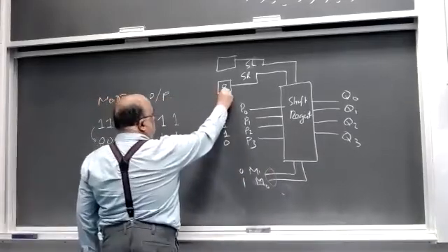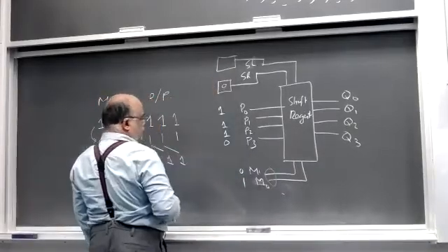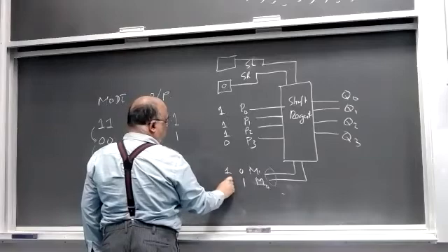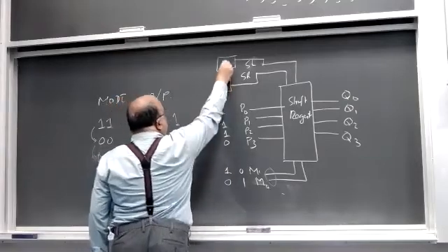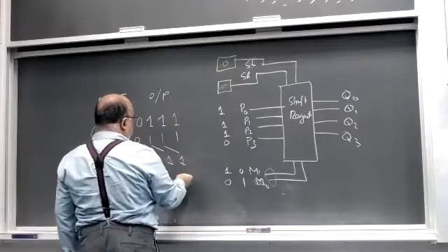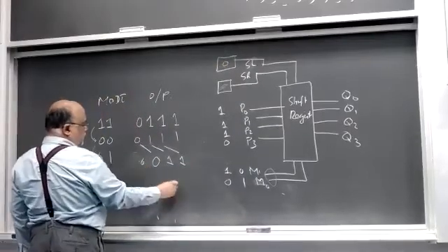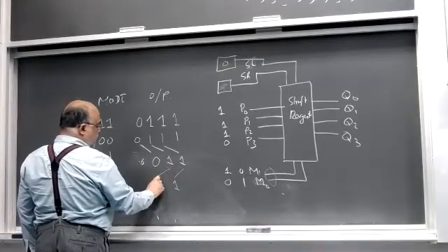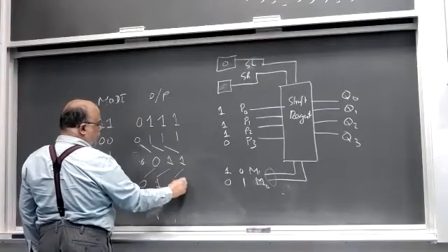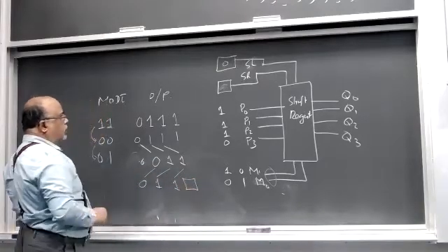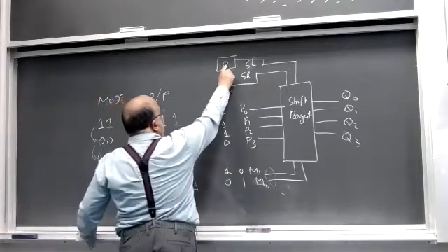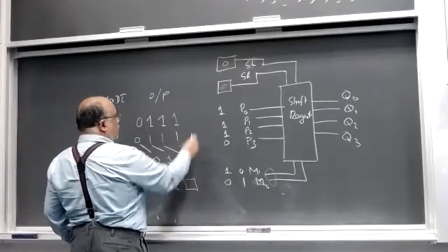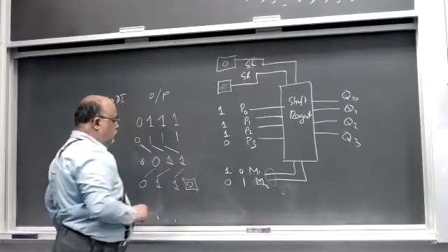उस वक्त ये वैल्यू मैटर करती है, ये डोंट केयर। इस स्विच को हमने क्या सेट किया हुआ? जब 1 0 करता हूं तो फिर ये वैल्यू डोंट केयर हो जाती है, ये वैल्यू मैटर करती है। इसको 0 किया हुआ या 1 किया, क्योंकि उसमें से इधर को शिफ्ट करना है। तो अगर इसको मैं अब शिफ्ट राइट करता हूं तो 1 इधर आ जाएगा, 1 इधर आ जाएगा, ये 0 इधर आ जाएगा। यहाँ पे इस खाली कुर्सी पे कौन आएगा, वो डिपेंड करता है आपने यहाँ पे शिफ्ट लेफ्ट इनपुट पे क्या सेट किया हो। अगर यहाँ 1 सेट किया हो तो 1 आ जाएगा, 0 सेट किया हुआ है तो 0 आएगा।